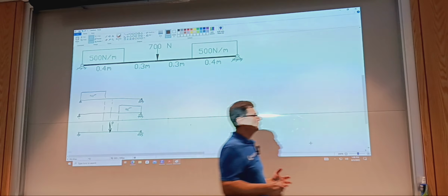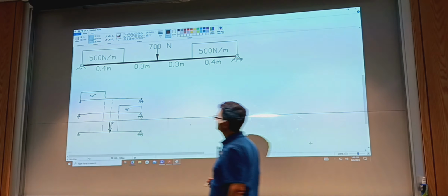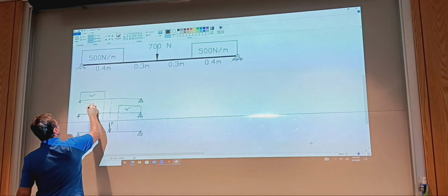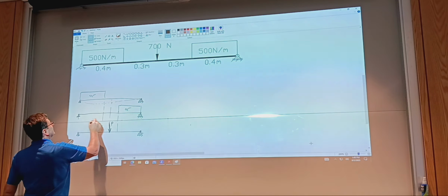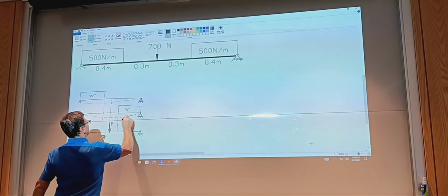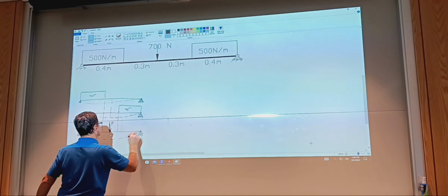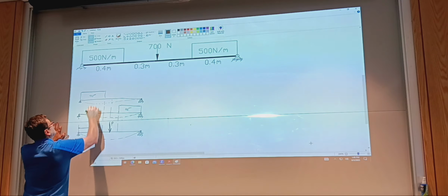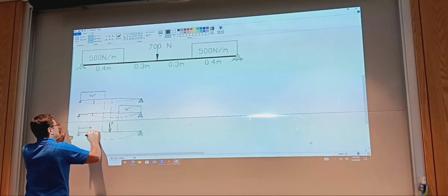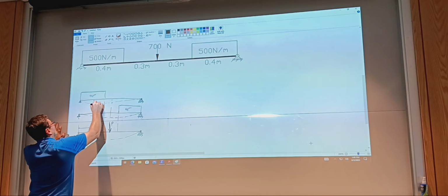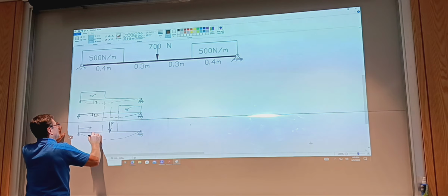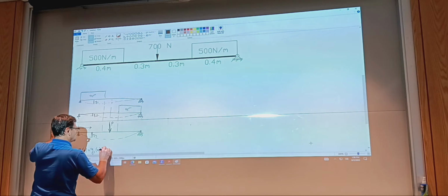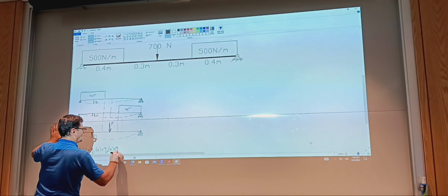And let's say we want the equation of the deflection. So due to W alone, the beam will deflect probably something like this. And then it goes like this, just a mirror, and then this one. So for example, if I'm interested in the deflection at some distance x, I take this piece, I take this piece, and I take this piece with their sign. So it'll be y1, y2, and y3. And y of x would be y1 at x plus y2 at x plus y3 at x.